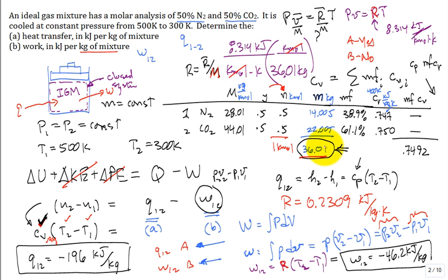How did you solve for the mass fraction for the specific heat at constant volume? This is 38.9%. I know that of this, it's 14 divided by 36.01. Then I just multiply the mass fraction times the specific heat at constant volume, put a number here, and sum them up.